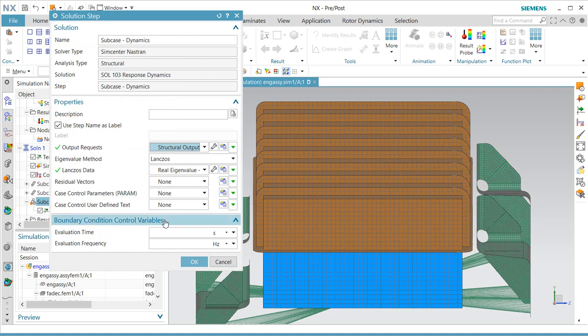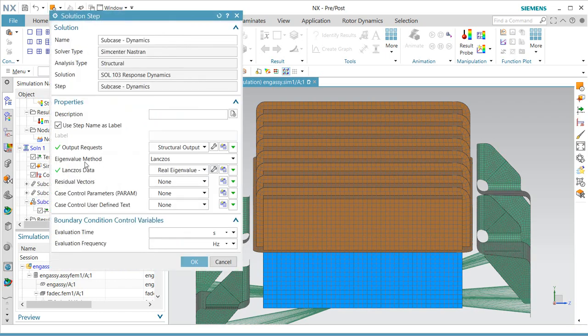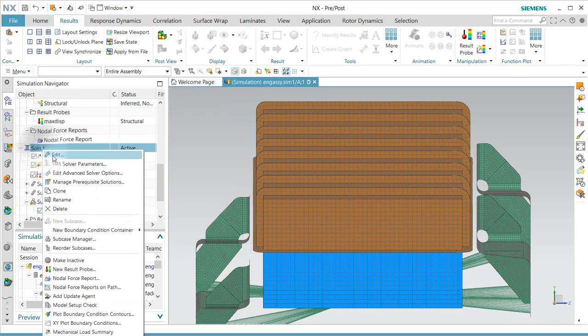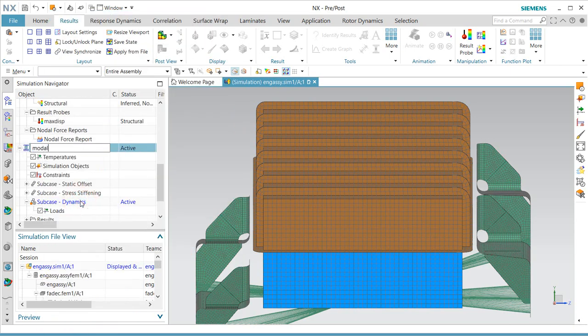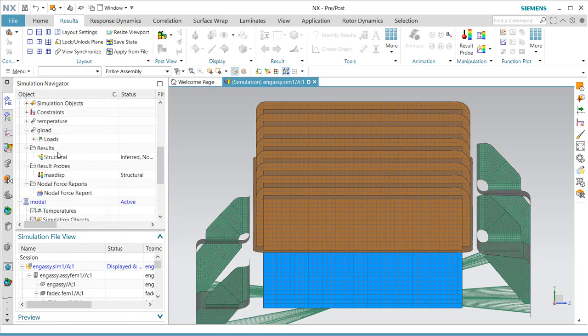And because we're evaluating an electronic box mounted on a fan case of an engine that spins at 6,000 RPM, the frequency range of interest is going to be between 1 and 100 Hertz if we divide the 6,000 by 60 to get RPM into Hertz. But we'll go up to 200 Hertz because we'll go 2 times the frequency range of interest.